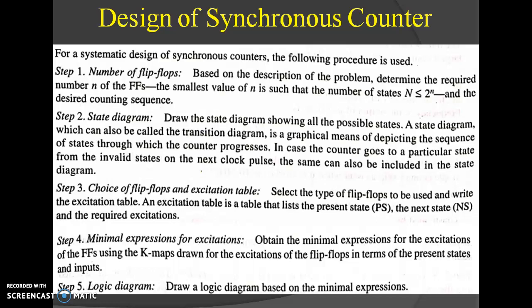Design of synchronous counter. For a systematic design of a synchronous counter, the following 5 procedure is used. Step 1. First, we have to look at the question to understand how many flip-flops we need. Step 2. State diagram. Draw the state diagram showing all the possible states. Step 3. Choice of flip-flop and excitation table. Select the type of flip-flop to be used and write the excitation table.